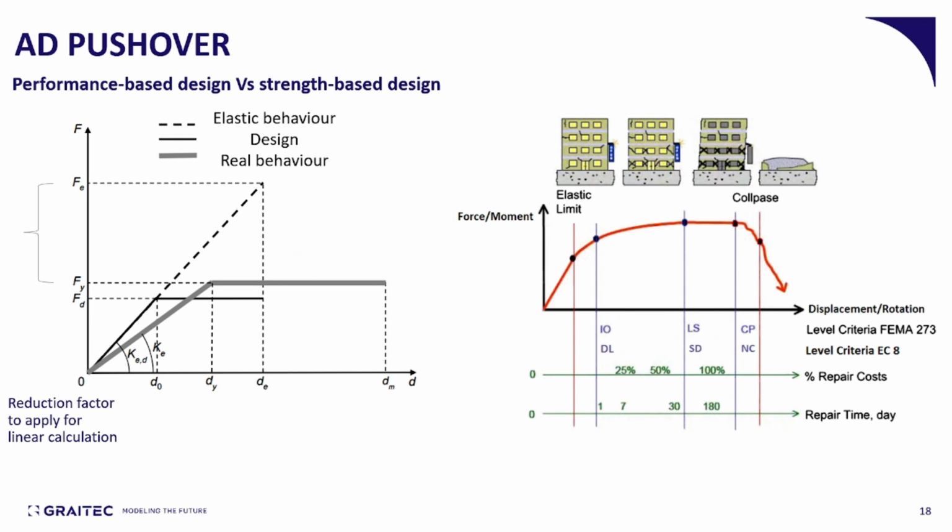The pushover analysis sets the discussion for two different types of design: the performance-based design and the strength-based design, as we call them. Let's start with the strength-based design. On the left-hand side, you can see this graph where three different types of behavior are described. The elastic behavior. This is the behavior of a structure when we design assuming elastic behavior.